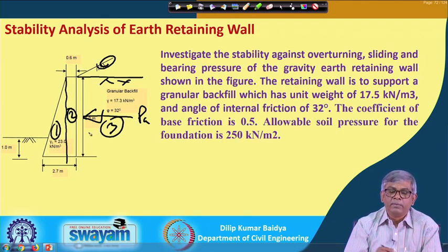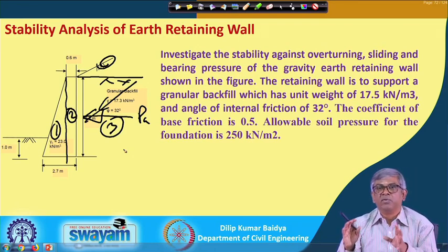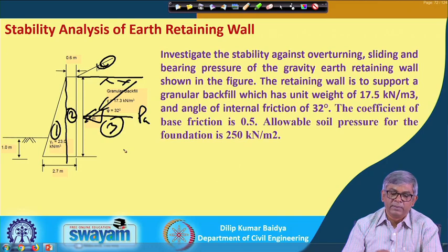This is one type of problem. I have taken a little complicated one, with a sloped backfill. Because of that, this pressure was like this, and then I have taken two components, PAV and PAH, and then I had to consider 4 forces, and then I have done the stability analysis.